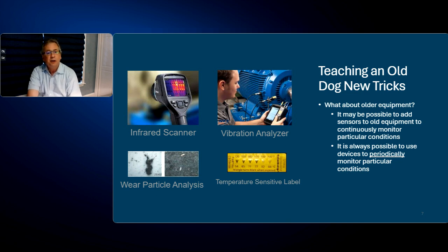Now, what we would do here, I don't know if you can see my cursor, but we would draw a vertical line kind of where the limit would be. And this is pretty simple. This could be a maintenance person checking it at some predefined frequency. It could be an operator because it's so simple. And drawing the line so we know what the trigger is to trigger an appropriate maintenance activity. Say it's a motor. It's getting warm, but it's hitting that limit.